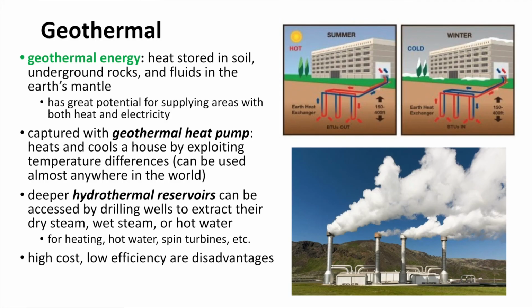Geothermal is great. I think everyone should be involved with geothermal energy. Heat stored in the soil and under rocks, and warm water that is in our mantle that is heated by Earth's systems has great potential for supplying areas with both heat and electricity. So it's almost a cogeneration in itself, and a very natural one. So usually what will happen in this case is we will have a pump system that pumps water down, and underground that water will start to be heated. As it is being heated, we pump it back up, and we're able to warm our homes.